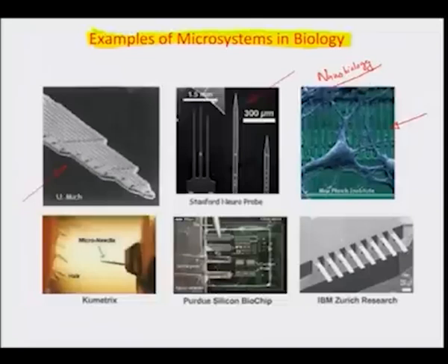So essentially the idea is that these neurons are growing over the gate region of these MOS transistor arrays, and if there is a change in the surface protein expression of these cells, it is recorded in terms of change of surface potential. And so if you can keep on monitoring the current based on the change in surface potential, it can give you an idea of what crosstalk is going on at a single cell level between many cells growing together on the top of this array.